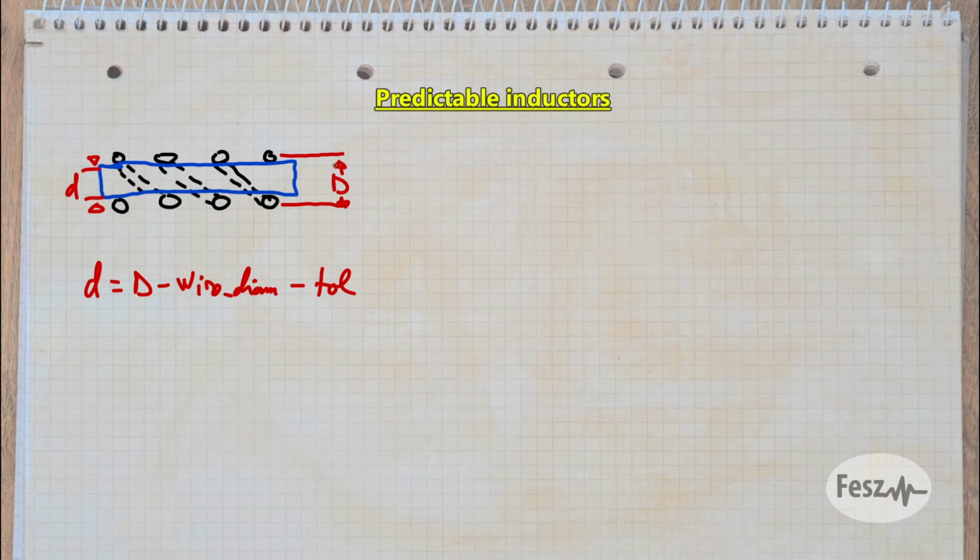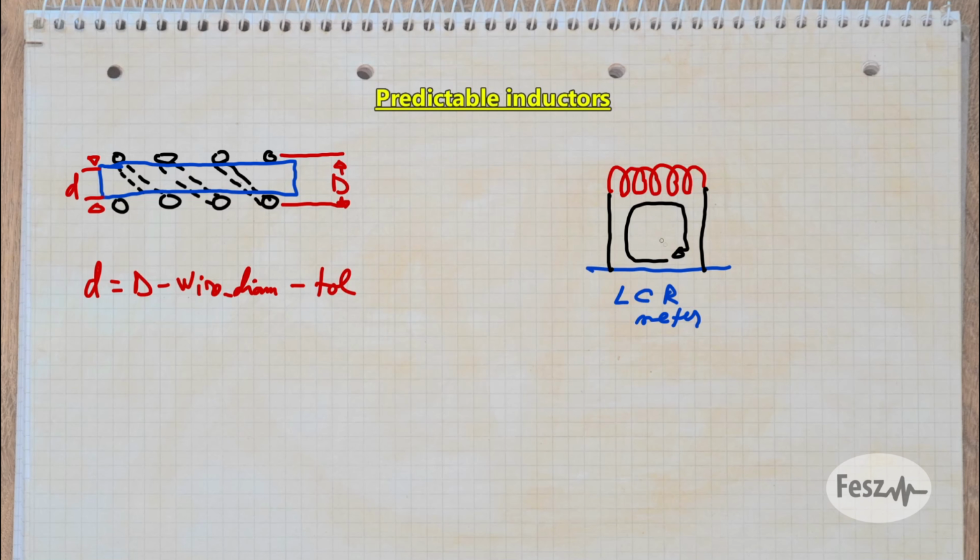The second thing to consider is that the calculation strictly refers to the coil. Once you connect this to something, like the LCR meter, well, you need leads to perform the interconnection. And especially with very small value inductors, these leads will be able to create a significantly large loop to impact the total inductance. So your inductor should target a slightly lower value than you actually need.